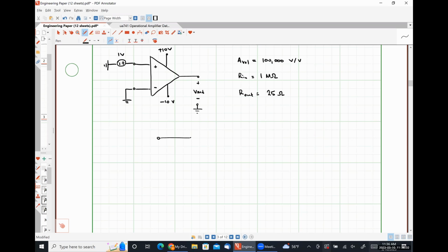So I'm going to start with the op-amp model by itself. So here is Rn. This is V plus. This is V minus. Over on this side, I have my dependent voltage source. I'm just going to leave this as AVOL times VD for right now. Let me make sure that you guys are aware that this is VD.